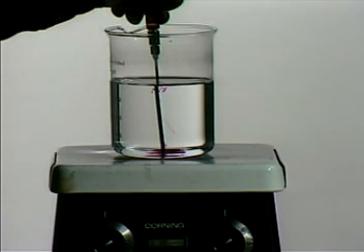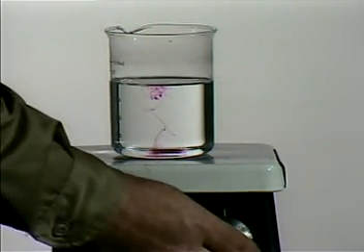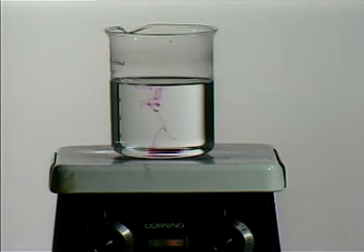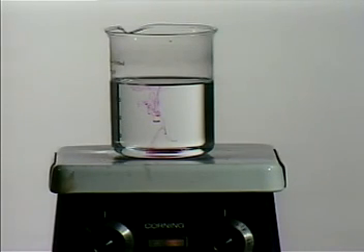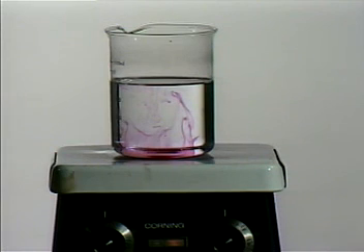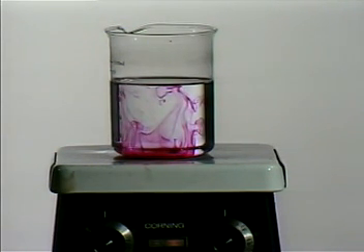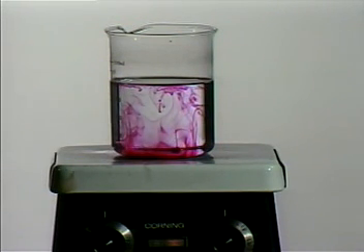We'll use this container of water and dye to show how natural convection works. When heat is applied to the container, the water that's closest to the bottom of the container is heated first. As the temperature of the water near the bottom increases, that water becomes lighter or less dense, and it moves upward in the container. At the same time, the water near the top of the container, which is cooler and heavier or denser than the warmer water, moves toward the bottom of the container. This is what happens during natural convection.